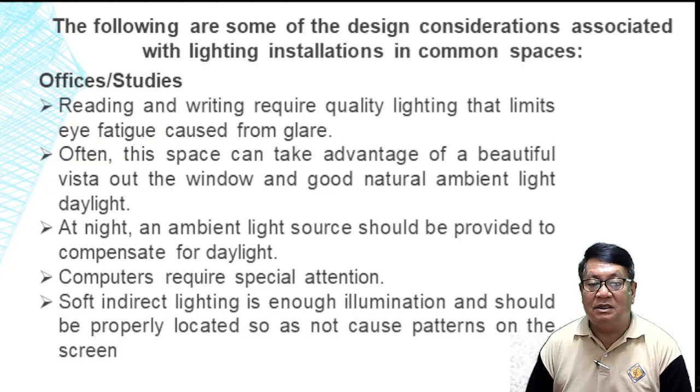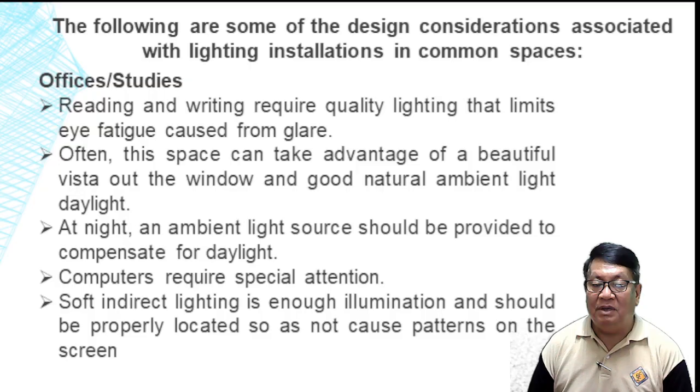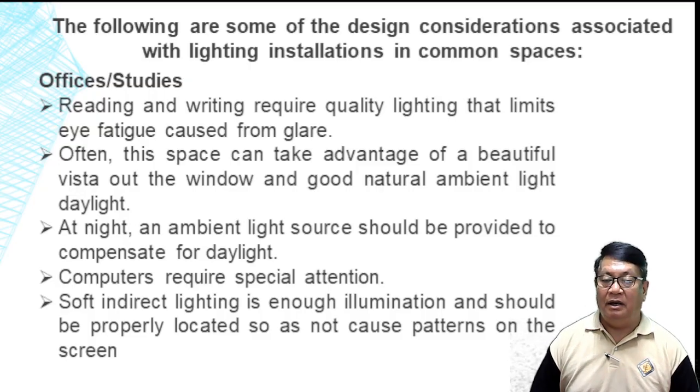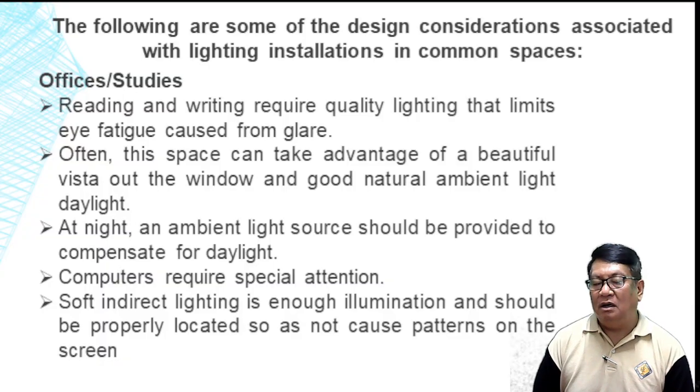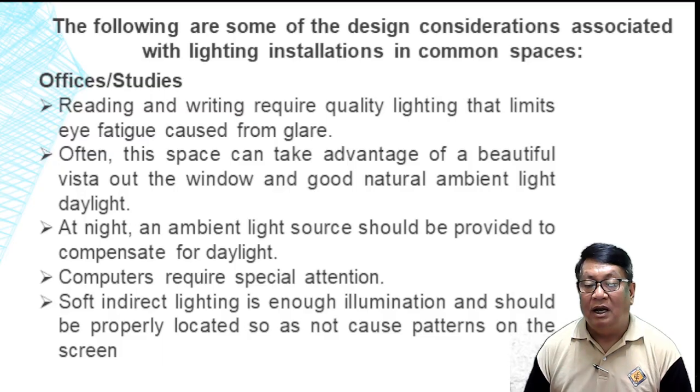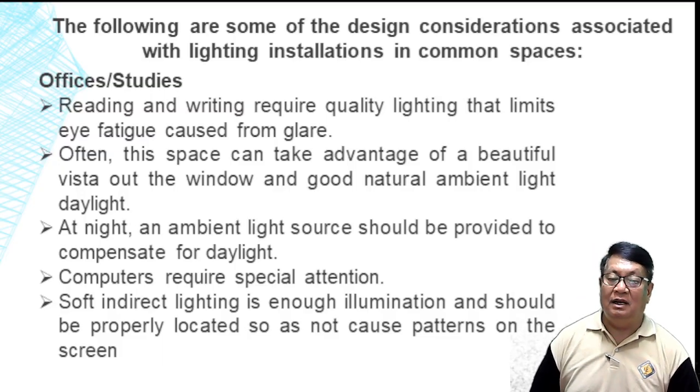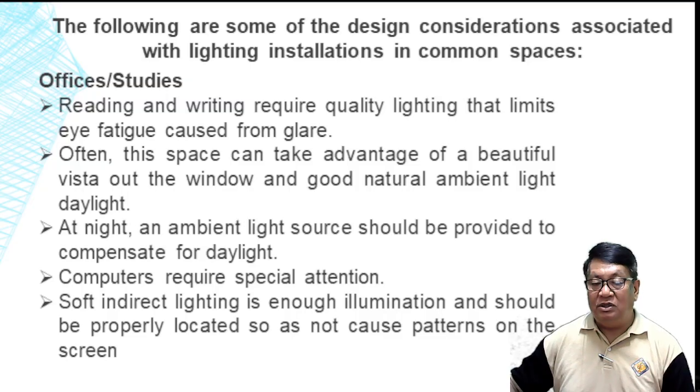Okay, so we have also offices and studies. These offices or studies, reading and writing require quality lighting that limits eye fatigue caused from glare. Okay, so we should consider our lighting system, especially if that area is used for reading, writing, and other academic activities. Okay, so open the space to take advantage of special beautiful vistas out the window and good natural ambient and daylight. Okay, computers require special attention, so indirect lighting is needed and should be properly located.